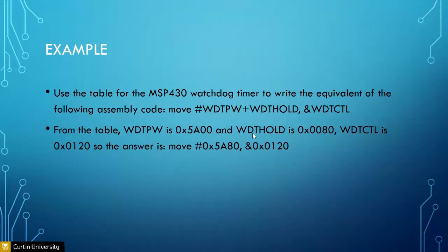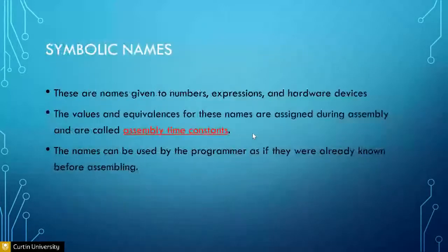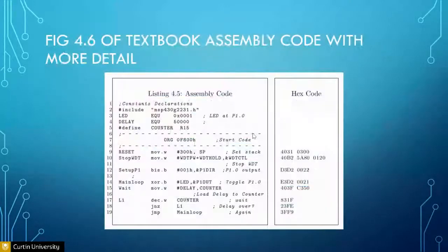All right. So the watchdog timer is important for you to automate the reset of the embedded system. If something happens to the embedded system, it will auto reset. Okay, if a question asks you, what happens to this code if I remove line number 10? Now this is a valid question. It has come out before. What happens if I remove this part of the code? It means the watchdog timer will kick in, and if you don't service it in time, the whole embedded system will go into reset mode.